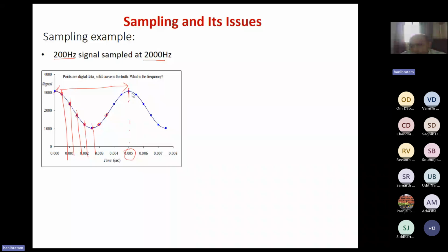But the digital output may not be directly useful to drive some physical system or some motor. So we might need to convert it again into an analog signal using a digital to analog converter, so that the analog signal I finally get will be a noise free output, and you can use it to drive a motor or whatever system you want to trigger or drive. Here we are doing this analog to digital conversion just so that the digital data can be processed in your processor or the DSP board itself, so that you can do a very highly accurate filter operation.